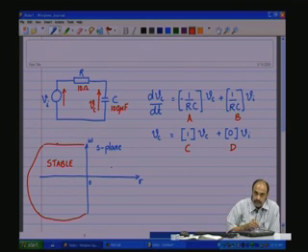And the right half of the S plane implies that if you have a pole on the right of the S plane, you will have an exponent to the power of whatever a or b t, and then you can have a growing exponent, which is an unstable condition, and that is why the right half of the S plane is called the unstable region.